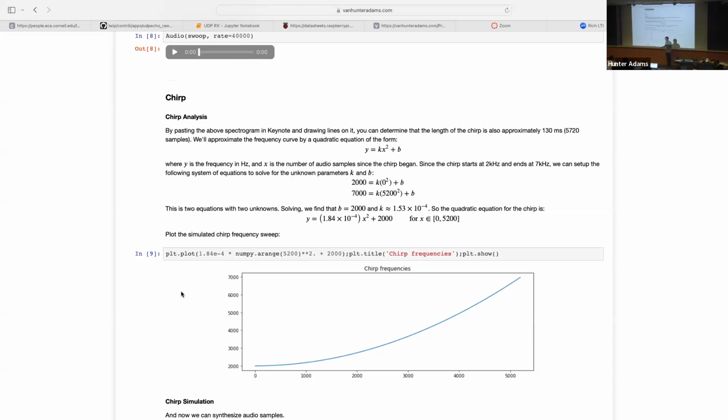And you don't need a fancy integrator here. You could do a straightforward Euler integrator. The consequence of that would be, instead of computing this function to get your frequency at each time step, what you would do instead is Euler integrate the derivative of that function, and it changes all this math into, I think, a shift and an add. Even faster than the multiply.